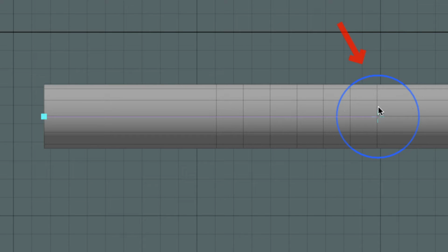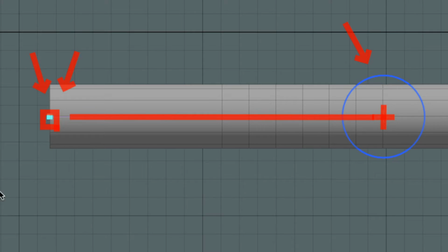Here in the center of that circle, we have an X, or a cross. That cross represents the start of the bend, okay? That's where things are going to fire off initially. So in every sense, what's on the right side of that cross is not going to be bent. Inversely, on the other side of this purple line here, we have a cube. This cube represents the end of the bend. So the cross represents the start, the cube represents the end of the bend.